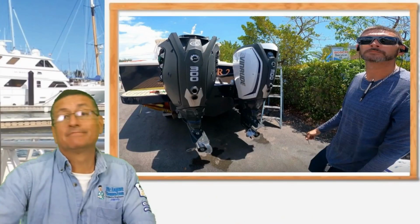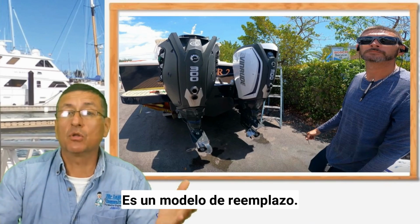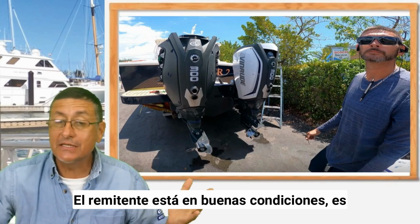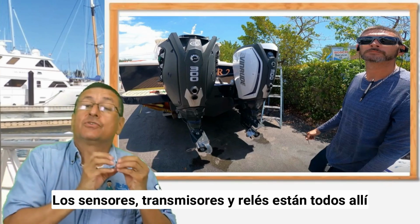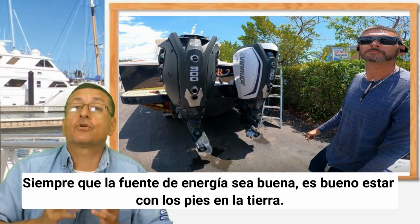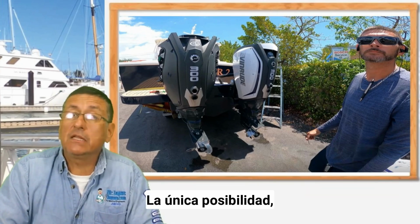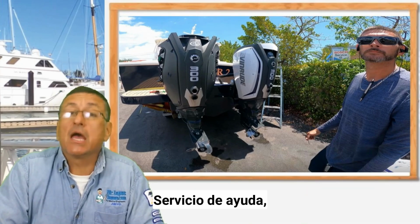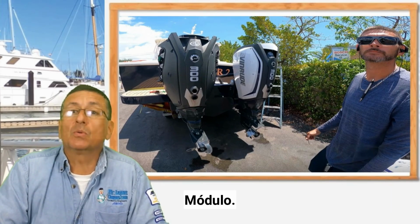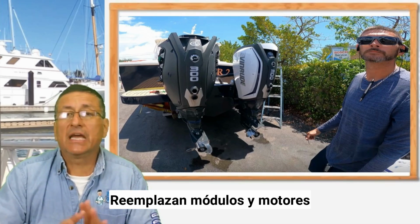Yes, in this particular case, the solution is to replace the module because the sensors are good, the sender is in good condition, the harness, the sensors, the sender, and the relays are in great condition, the source of power is good, the ground is good. The only possibility, according to the help desk and the manual, is to replace the module. They ordered the module, they replaced the module, and the engine starts perfectly.